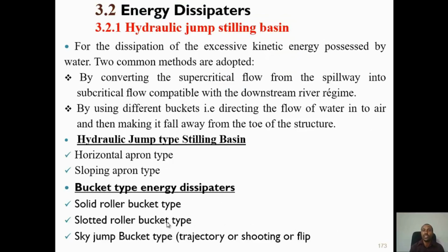The next topic is the energy dissipator. You should dissipate the incoming energy, or the energy of the flow of water downstream of the spillway. Otherwise, erosion danger will be high. The hydraulic jump stilling basin is the first energy dissipator.